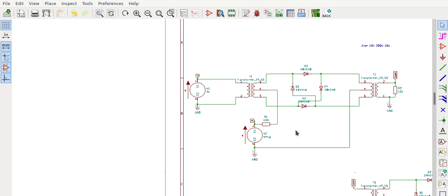Okay, so if it is a logical 1, it is connecting directly these 2 transformers, and if it is a logical 0, it is connecting in a cross connected fashion. Or we are doing a 180-degree phase reversal when it is a logical 0. So that's how this circuit works, and we have just a current limiting resistor connected to this voltage source, otherwise if we don't have that, then we will have very large amounts of currents flowing through these diodes.